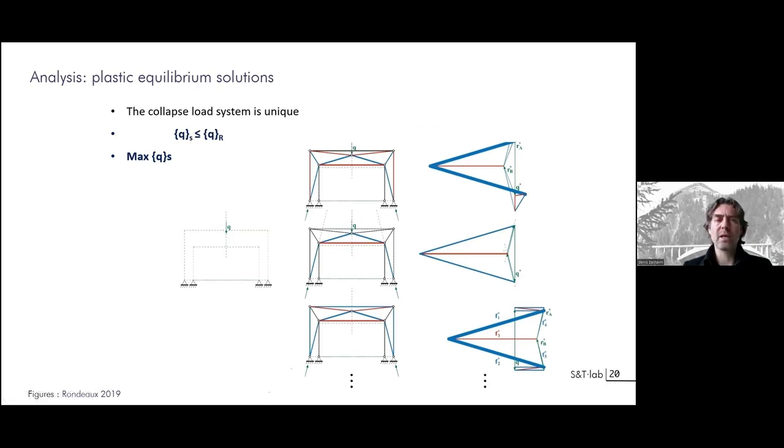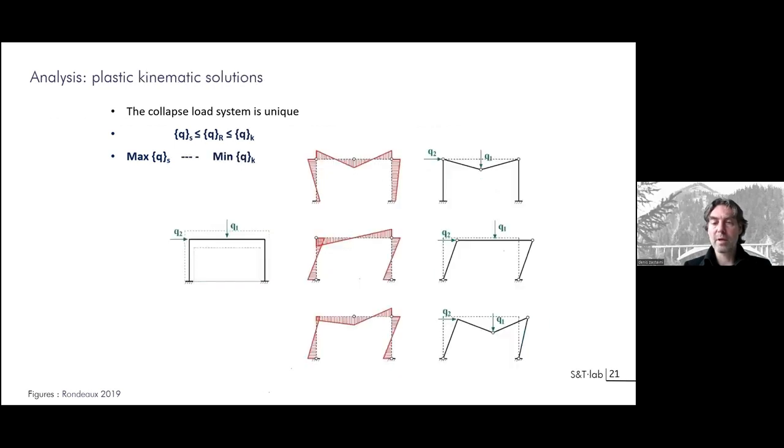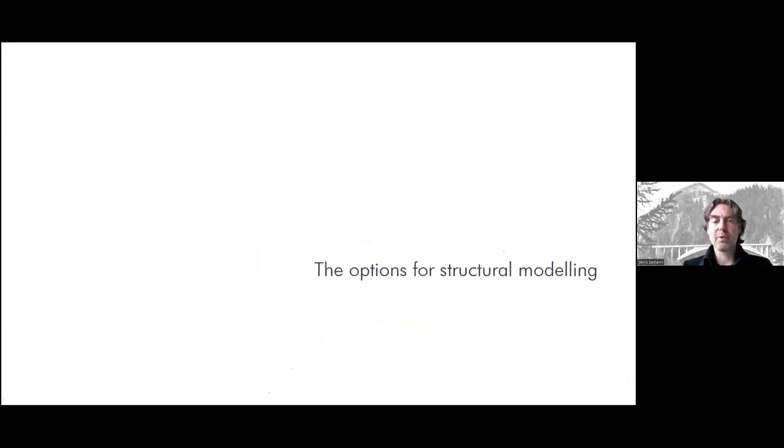So that's for the elastic analysis, on the side of the equilibrium theorem. If you go to the plastic theorem, you see that when you reach the limit of elasticity somewhere, we will be developing hinges. In this case, you will see hypotheses in which you are developing hinges in several places, and you are just assessing what would be the possible solution, and the minimum will correspond to the limit. So that's a connection, and with both together, you will have the final solution.